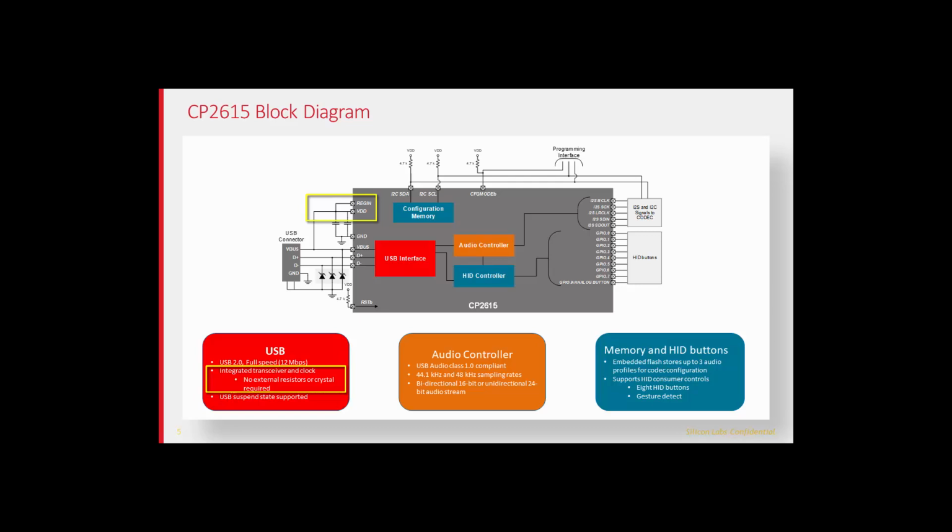And I've mentioned some of these throughout this discussion already, but we offer, for instance, an I2C interface on the 2615 that can be connected to a number of other components on the embedded side. So we provide a bridge from an Android phone into whatever components the end product has, so that without any kind of coding on the embedded side, we're providing these customers with a way to communicate with all the other components, maybe sensors, maybe other MCUs on their end product. We also have a UART interface that functions similarly. So we give customers these little bits and pieces.